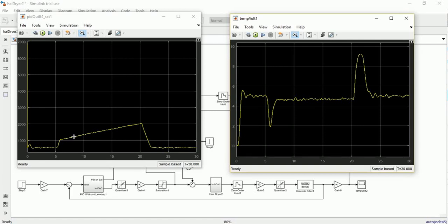This accumulation is called windup, and it will accumulate during the error. When this error is still there, there will be accumulation. If nothing happens here, this will continue this trend, and the longer it takes like this, the worse. So at this point, when the disturbance ends, we need to go back and try to recover our normal state and go back to our reference. But because of this accumulation, it takes a long time. It takes all this time to get back to normal levels again.